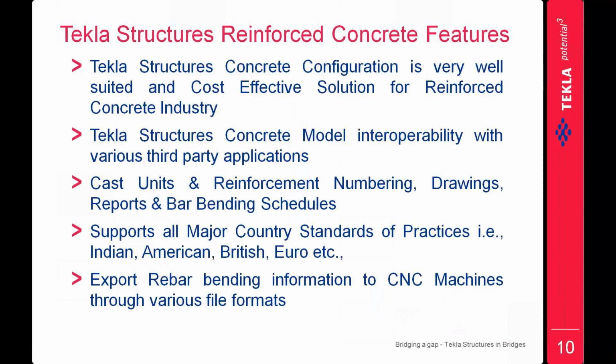And most of our customers say that Tekla Structures, in the area of reinforced concrete, is a cost-effective solution, and it has model interoperability features with third-party applications, so that we can transfer the model to any third-party application. At the same time, we can bring it back. And from the model, we can generate the cast units and reinforcement, we can do the numbering, so that for each and every rebar, we can give the proper bar mark number, and we can generate the drawings, reports, and the bar bending schedules.